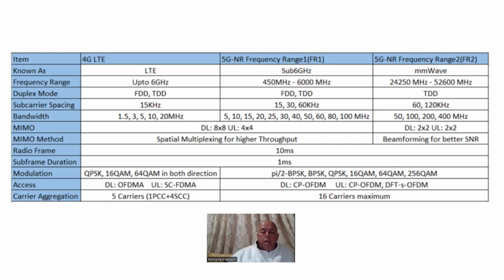But at least for right now, I ran two versions of this. I ran one baseband section that I have built up from discrete components, and it's just a plain random 64 QAM signal. I didn't worry about regenerating and shaping it as an OFDM signal. As you know, the OFDM spectrum for the 200 megahertz channels is not going to be the same as really the 64 QAM with a filter shaping. So it's a little bit different, but it's close enough.